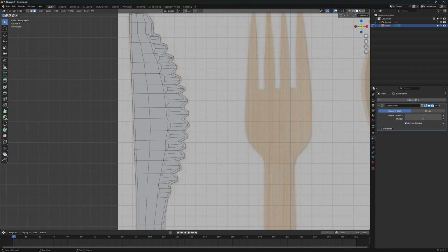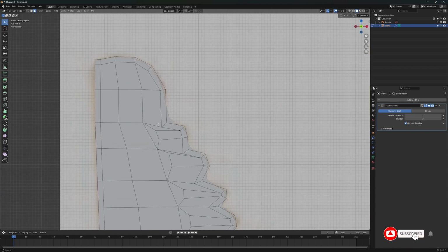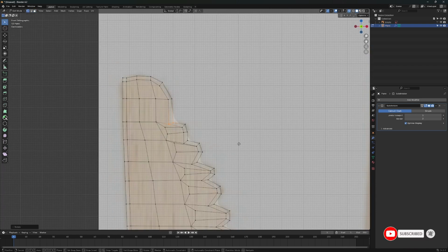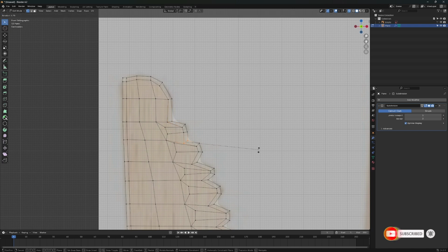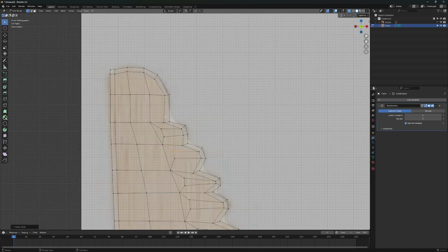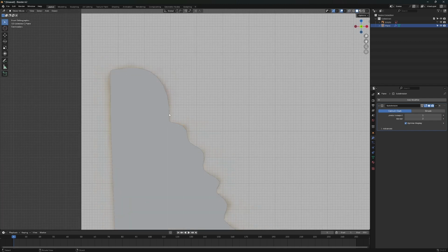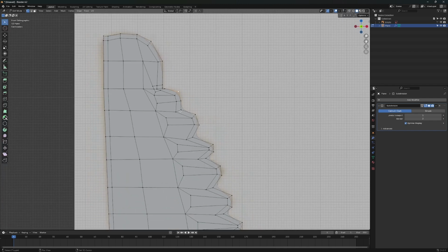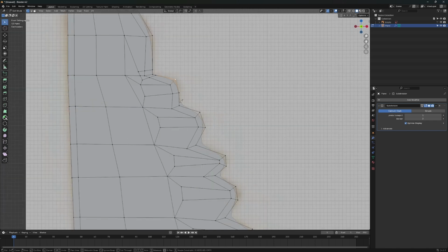Now we'll make some of the areas of the right side sharp. Adjust those vertices too close to some of the other vertices. Then select the knife tool and cut through the parts that you want sharp. Then cut like this as well. You can see that it looks sharper than the other parts. Now you can do the same for the others.